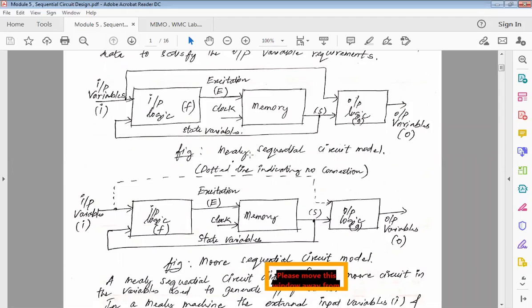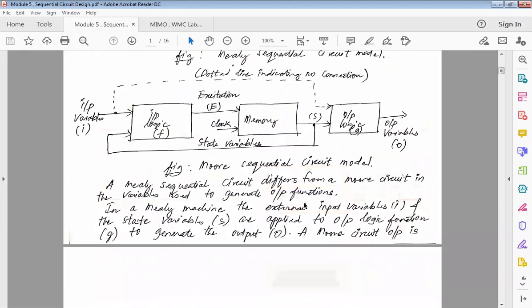And we call it Mealy because the output is dependent on what? Your memory as well as your input. So input by output, this becomes your input, and this becomes the output of memory. In the Moore machine, the output is only dependent on the state. It's not dependent on the input, so the input doesn't come inside the state diagram. It comes outside. I hope this is very clear for all of you.